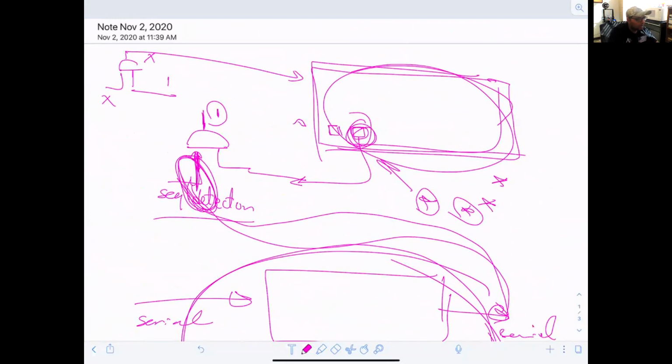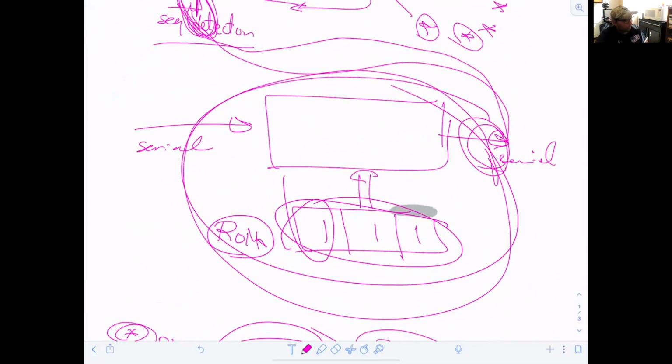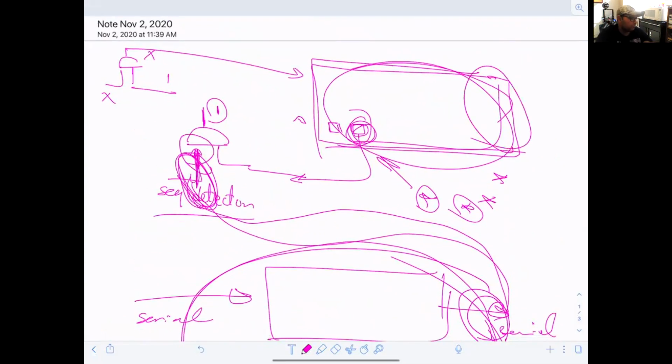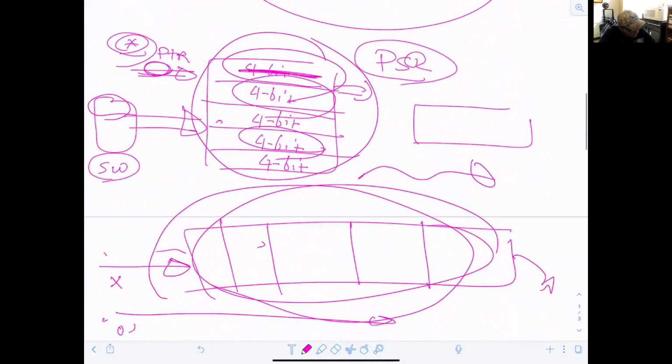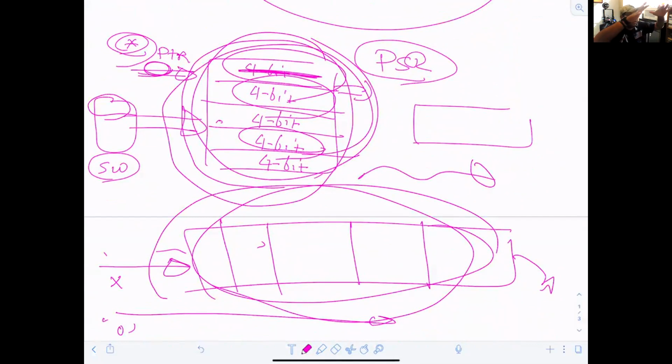So that means when I'm writing my test bench, what exactly should I add checking? I have to check the time of receiving the signal. So our target while we're writing the test bench this time is not just writing a test bench where 1 and 0 are coming out, it's the timing. When this one brings 1, how many cycles should it wait until it goes here, so it will turn on this block, for instance? Or how many cycles should it take for this memory to start sending data from the parallel shape to the serialized shape until everything goes smoothly one by one.